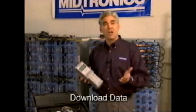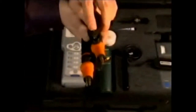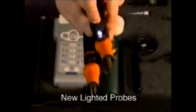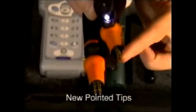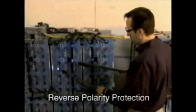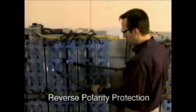The kit's interfaces and accessories have been improved with new lighted DuraProbes that are useful for locating secure contact points on leads in dark areas. The tips are pointed to help penetrate through deposits for a better contact. To protect its circuitry, the Ultra will not turn on and will display or sound a warning if the clamps or probes are connected in reverse, red to negative, black to positive.